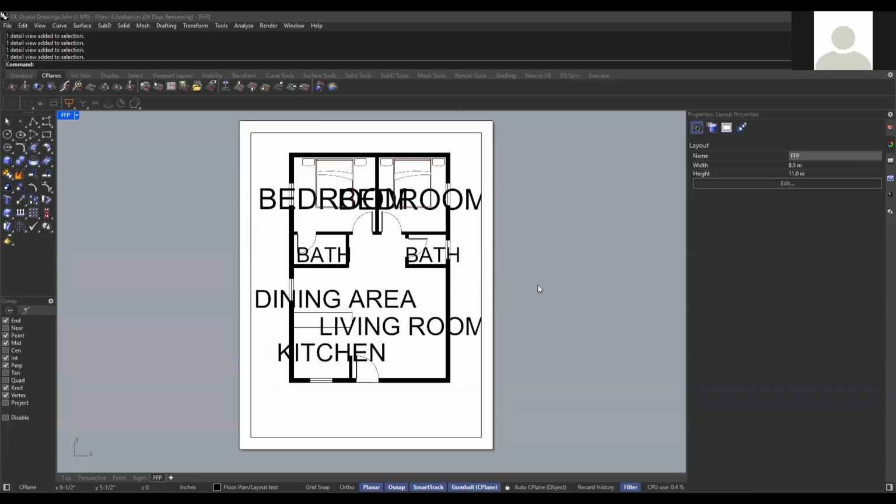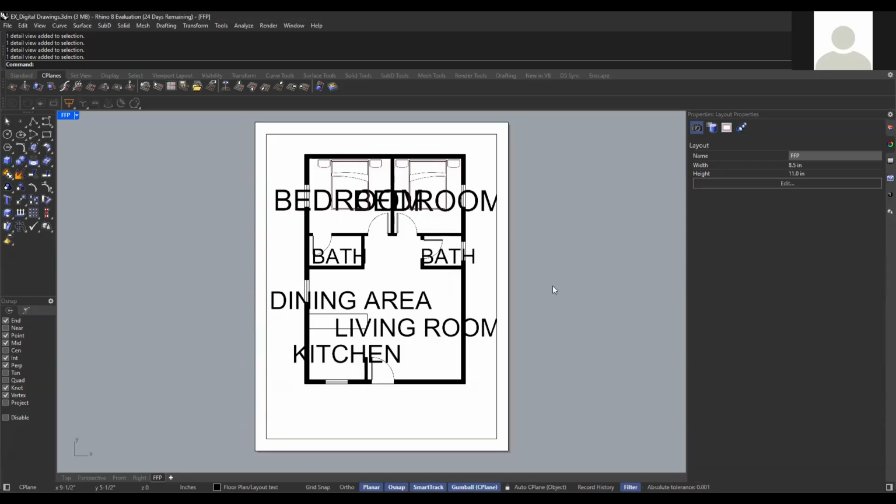Another thing is in layout, it's like the SketchUp layout that we work on. You can also create new layers for your specific layouts. For example, if you don't want to see this text, we have to rescale that, right? So if you want to label your drawings in layout, feel free to do that. I'm going to show you how to do it, or even add the dimensions. You can add all the details that you want to have in your drawings, so you can have it in layouts.